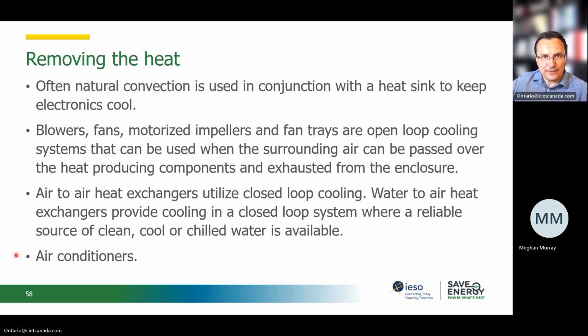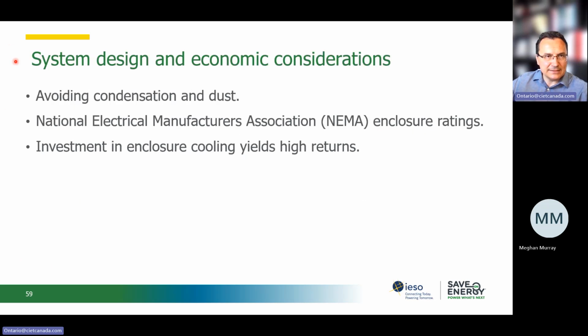outside. So for system design and economic considerations related to these systems, we try to avoid condensation and dust accumulation. We use NEMA standard for enclosure ratings, and we look at what would be the economic impact of designing this cooling effect, these cooling systems. So releasing the heat from our equipment.